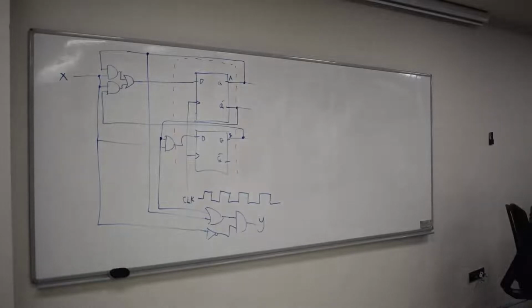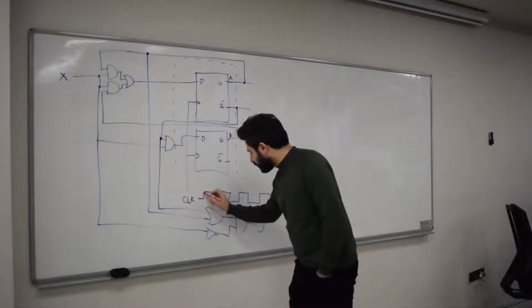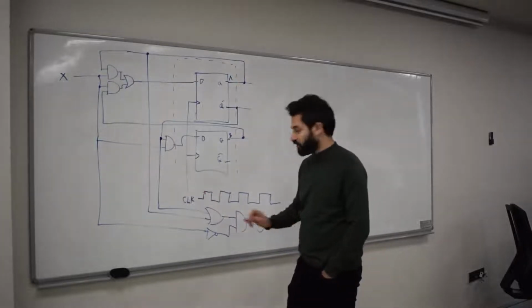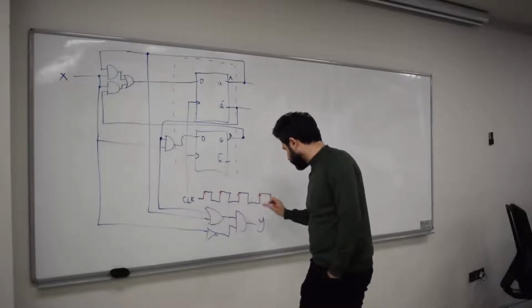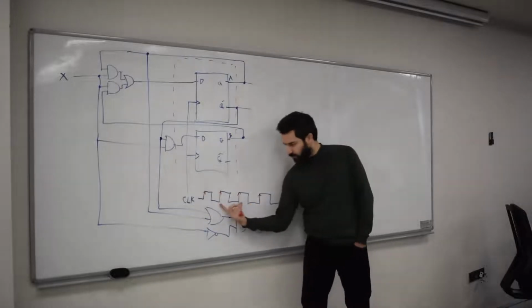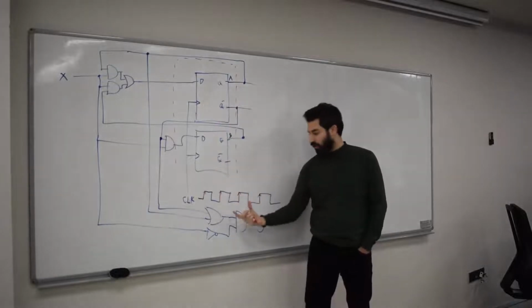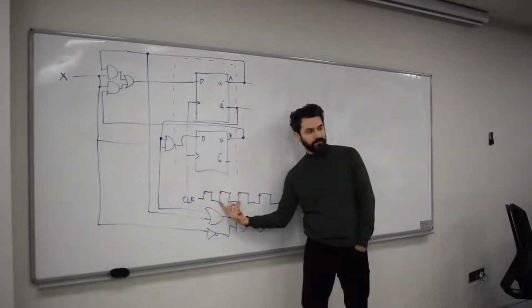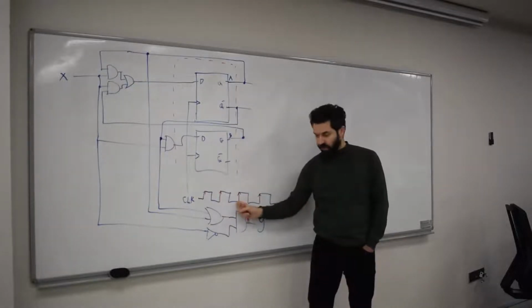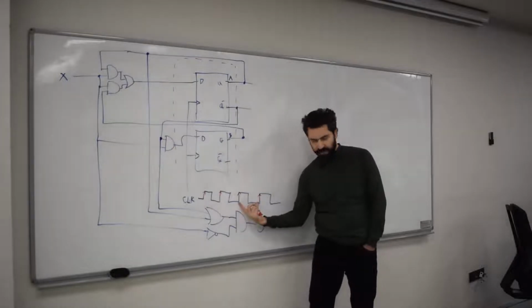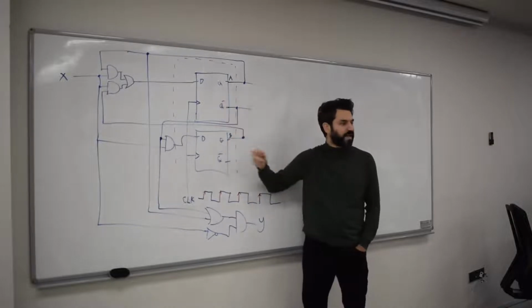And this circuit is a rising edge circuit, right? These flip-flops change state on the rising edges. In other words, this is where the state could change, and this is where the state can change, and here, and here, okay? What happens the rest of the time? It holds the value. Whatever it's storing, it's going to store for as long as this period. And then it looks at the input, and whatever it sees as the input, it changes state to that input, and then stays there for that period of time. That's how these two circuits behave, all right?